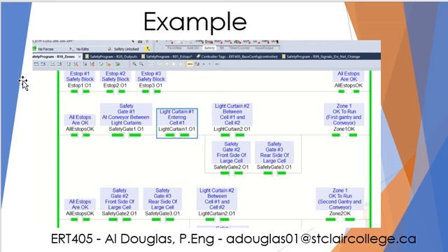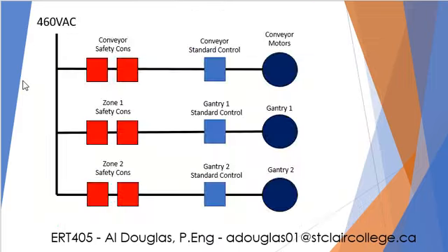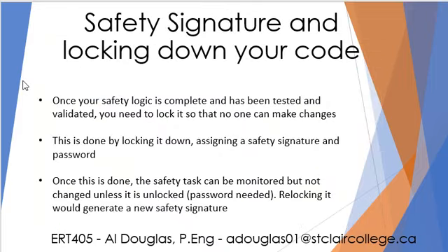And the .O1 outputs from all these blocks we can use in combinational logic within the safety task of the PLC to create different zones and things like that, to do whatever we want with safety logic as well. And that is the general idea behind safety logic.